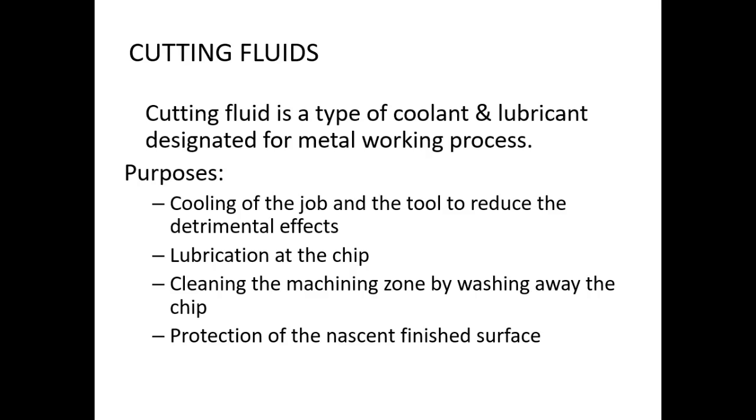The second one is that it helps for easy machining operations, so there are no difficulties that come across with the machining process. Third, cleaning of the machining zone. While the cutting tool cuts the workpiece, obviously chips are formed. These chips will be cleaned away by the cutting fluid. And protection of the nascent finished surface, which improves the surface finish. That is why we must use cutting fluids.